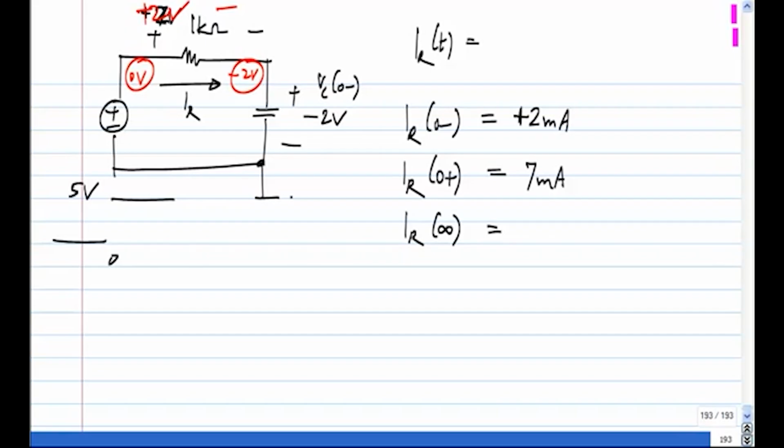You have to open circuit the capacitors. Okay. Because we are talking about piecewise constant voltages. So the steady state also will be a constant voltage across the capacitor. So that means that the current through the capacitor will be 0. Okay. In this case, it so happens that IR is the same as the current through the capacitor. So this is also 0.